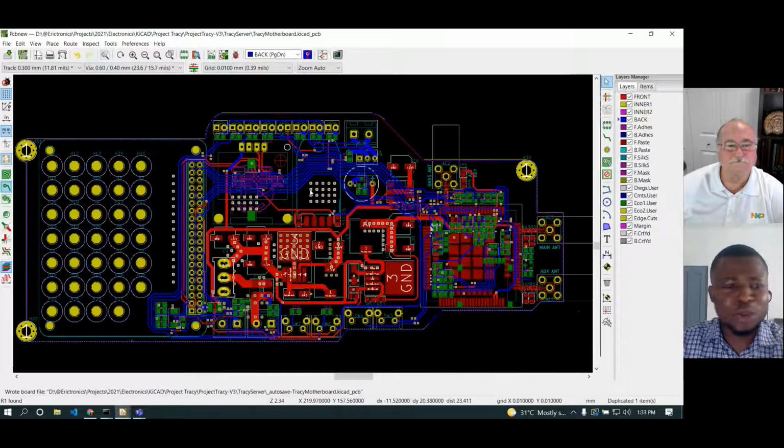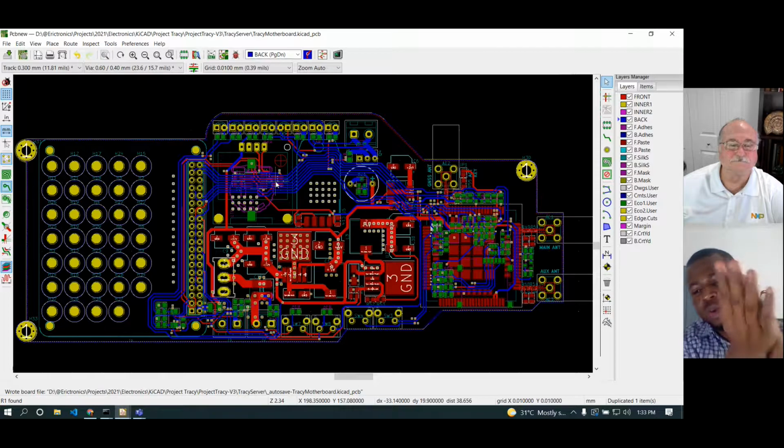Okay, so when we come to the stack up, it is a 4-layer board. And I actually employed what we did, the review we did last time. I employed those that I remembered. So this 4-layer board has ground pour on all the layers, and I routed the power, because I actually don't have many places with power. So I actually routed power with the plumbing, your divided pipe plumbing approach. So that was to make sure that power was going to where it was needed and not to flood the entire copper area with power. All right, so yeah, if you would like to take over.